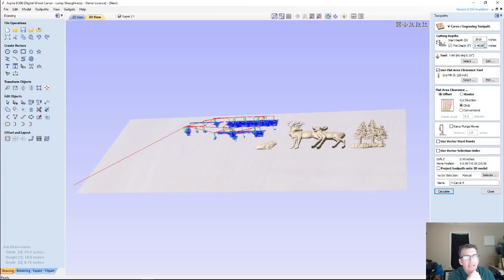If I'm starting here, this is the number I want to end up on, but I'm already down this far. I'm not starting from 3/4, I'm not starting way up there. So if I had been smart, I would have said 0.4884, where I'm starting from, minus 0.3471, my current Z plane. That gives me where I want to start and end up. That's my cut depth.